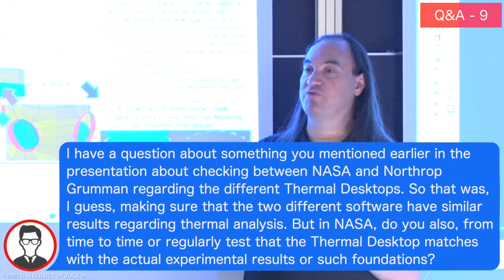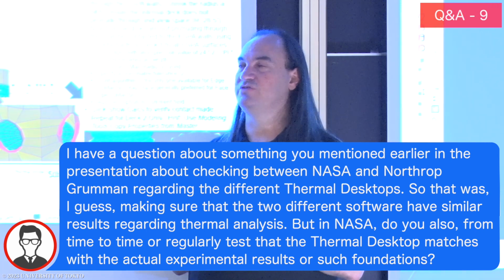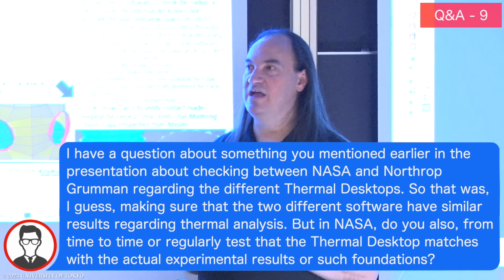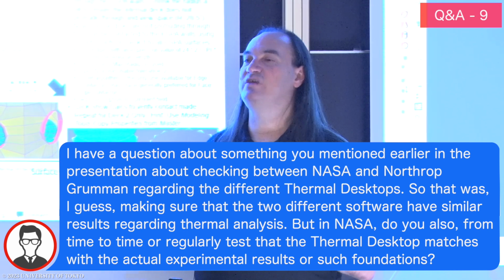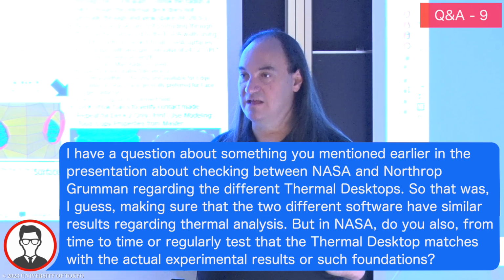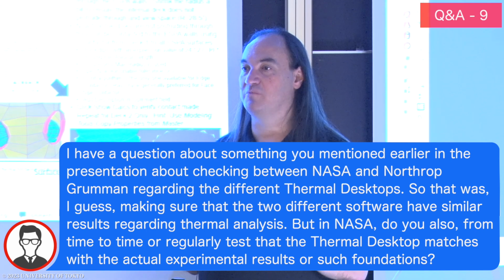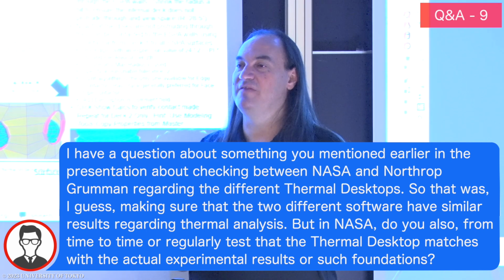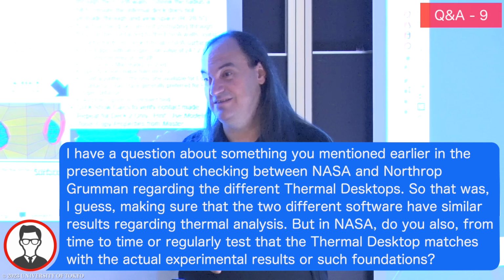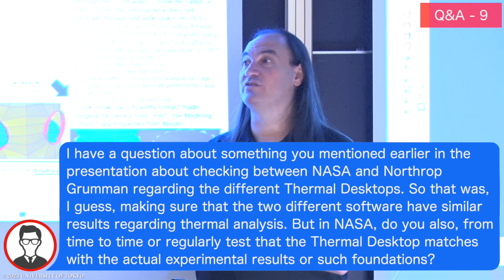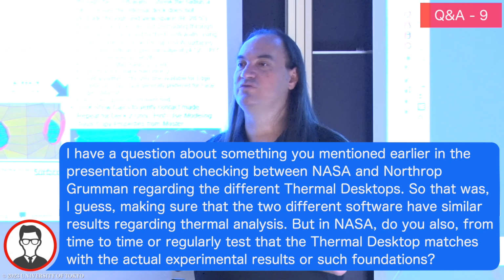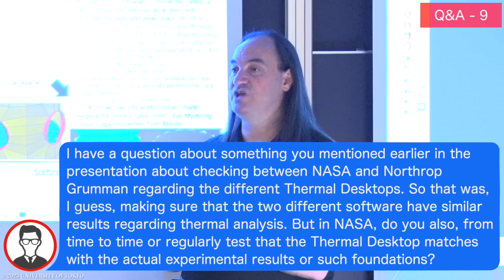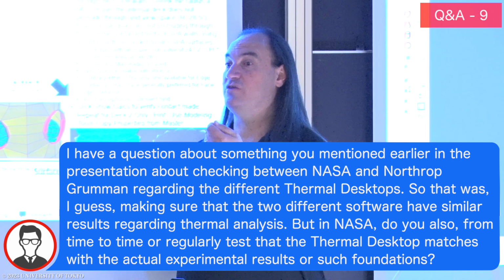Now, that said, for the Northrop case, JWST was so difficult to test, so large, cryogenic, there's so many new things on it that to reduce the risk, they had 2 teams of people modeling the design that tended to try to work as independently as possible. And if you both came to the same answer, you felt a little more confident that you both got it right. You might have both gotten it wrong, but you felt confident you both got it right. And if you saw discrepancies, you then said, okay, well, who's right, who's wrong? You looked a little bit closer at that area of the design to understand why one person saw X and the other person saw Y.